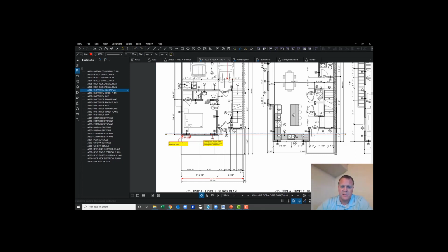And so what happens to this? Well, if the plumbing and stuff is in the floor cavity, then you've got to find a way to make sure that it is heated in our climate, right? So you can't have a water pipe in a cold wall without it being protected, or I can't remember the exact term, but it can't be in a cold wall without having heat on it. So some way to heat it.